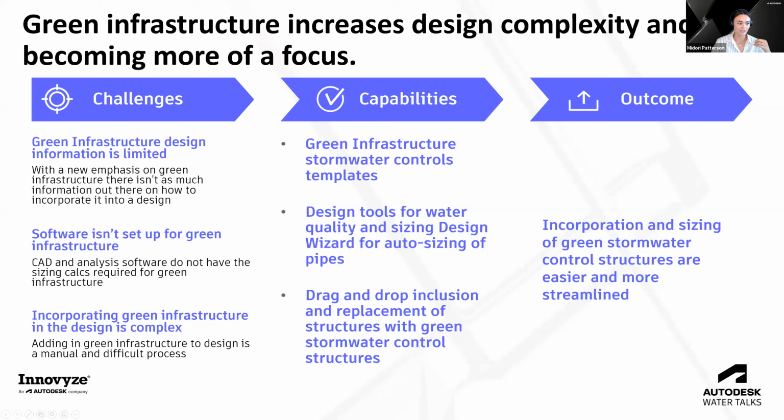And InfoDrainage solves the St. Venant 1D shallow water equations to calculate the discharge in each physical connection. But basically what that means for green infrastructure is that you can represent backwater effects. So you can model these treatment trains of green infrastructure, and you can link them up to achieve those lower discharges and avoid just a basic pipe to pond solution.